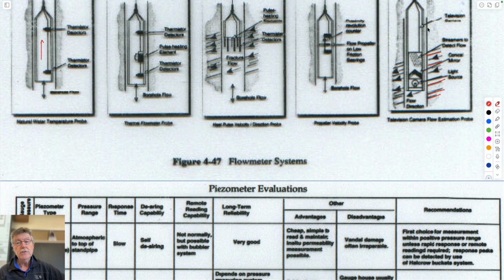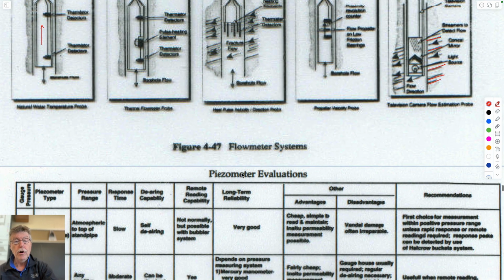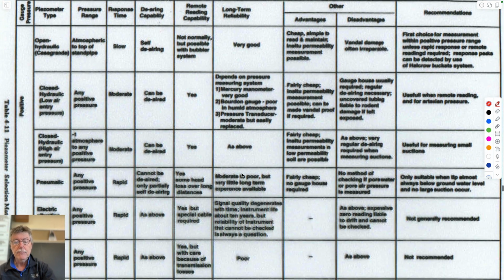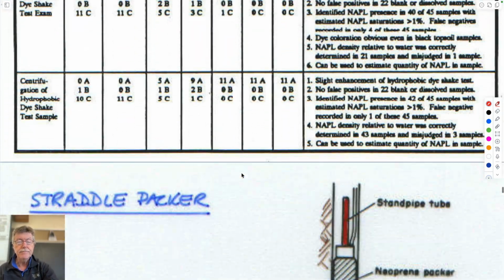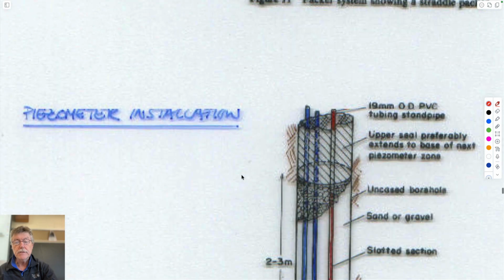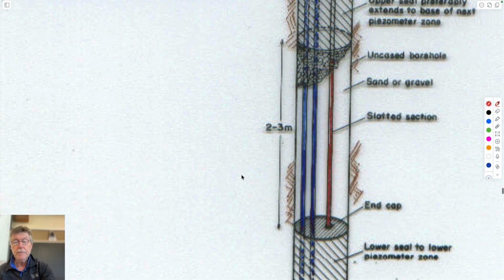And I guess the other thing you can do is sometimes if you have a static camera and you see little pieces of silt or particles going past it, you can use that to calibrate how fast fluid might be flowing in the borehole to again give you some idea of what's going on, whether it's an aquifer that's flowing or whether it isn't. Lots of other different things.